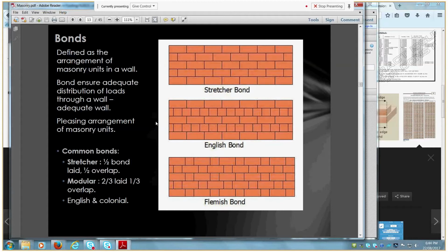Yeah, so at a firm I used to work for, we had an extension done to the office, and that was all done in cavity brick to tie in with the rest of the construction of the building, and that had your traditional plaster render, and it's fine if it's done properly. You can engineer your slabs, of course, to take all that load, but when you're going with either cavity brick or double brick construction, you have to be cognizant that there is a significant amount more weight that you're carrying there, and that might have been the issue with your builders.